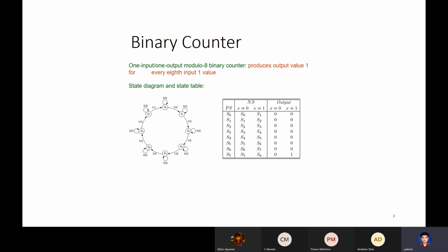And we have seen that it's a sequential circuit, even though we have not shown the design of the sequential circuits. It's very easy. You can draw the state transition diagram of the cascaded flip-flops in a register, and you can easily write down the logic for the state transition, depending on what kind of shifting you want.